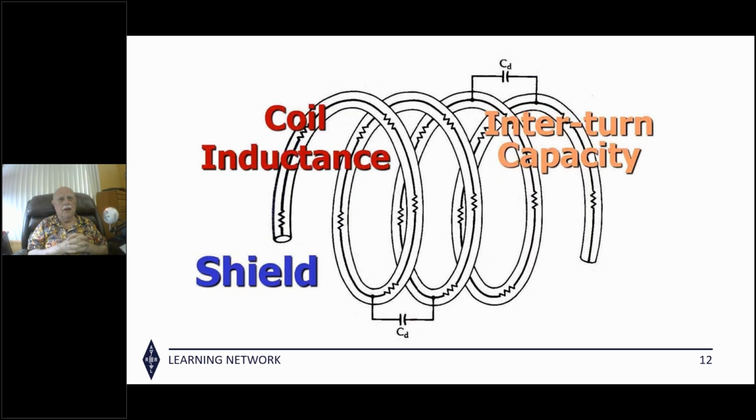49-to-1 impedance Baluns, or 7-to-1 turn ratio Baluns, are something I want to do a little more work on. I have a feeling it would be good to put some ferrites on the coax anyway. Never hurts you to do it. That's why when I'm building a new antenna or trying a new design that I don't know how it's going to work, I just Balun it to death with ferrite choking. What can you hurt? You can't hurt a thing by doing that, and you can't hurt a thing by choking off the end-fed long wire. Chances are the 7-to-1 that's used for the long wire will do the job, but I don't know for sure. That's what I'm going to have to look into more thoroughly.